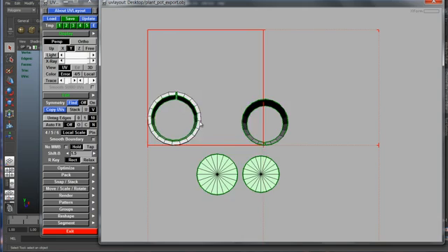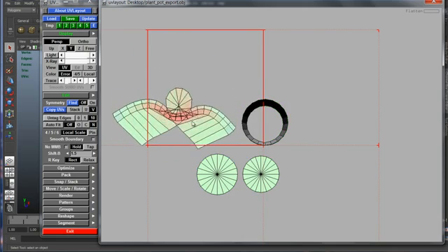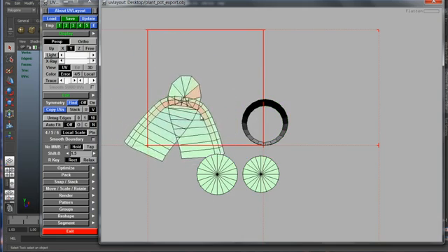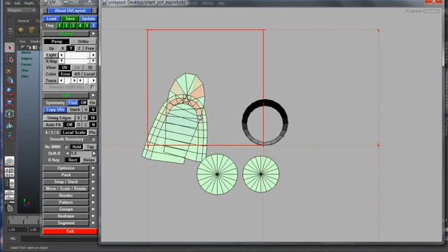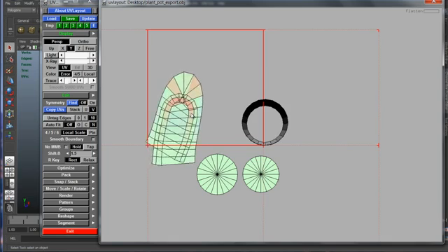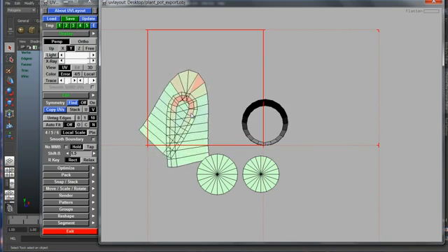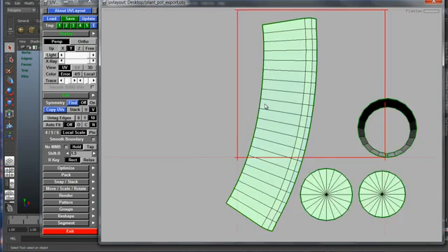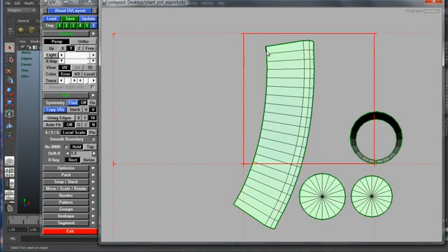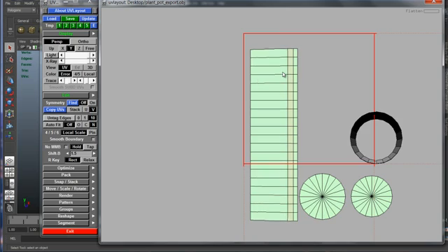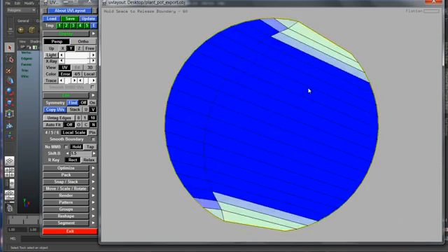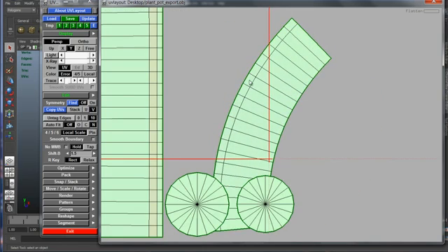I've just flattened both end caps. I'm just flattening the main parts of the pot. Again, Shift and F, and then with the I, selecting all the outer edges. Hold F, and now we have a straighter edge. The same thing with the other one.